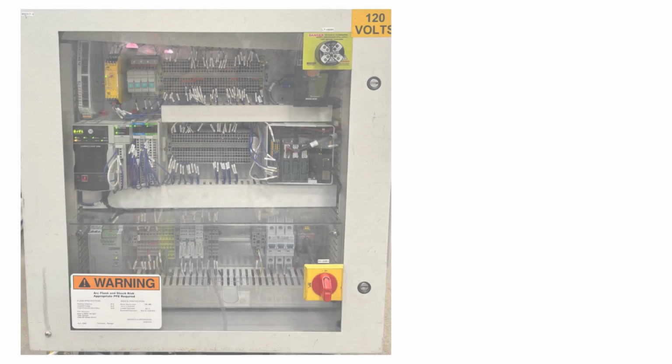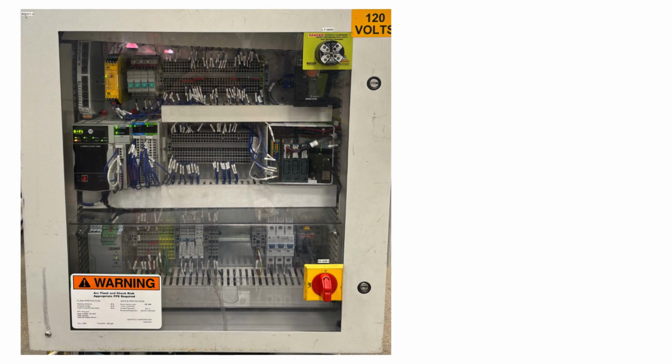Now for the control panel. The brains of the automated system is housed within the industrial control panel powered by Allen Bradley. The power distribution within the cabinet takes an incoming 120-volt AC single-phase power and steps it down with an industrial power supply to 24-volt DC to run the low-voltage control circuits, safety relays, sensors, and input and output modules. However, the primary in-feed driver motor is directly connected to a 120 AC supply for its main power.